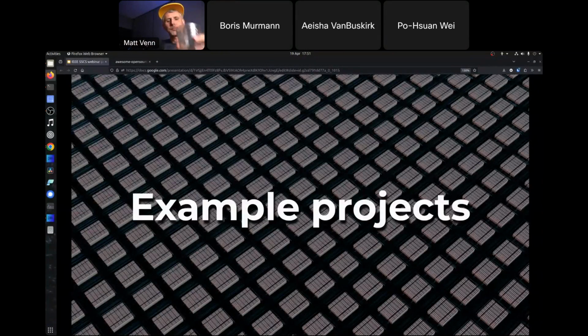What are the limitations of open source tools you shared in terms of process nodes or number of transistors, etc.? I would say probably 10 million transistors, order of magnitude. There's a lot of development. One of the big bottlenecks is that there's maybe 10 or 12 tools in the whole ASIC flow. One of the bottlenecks is Yosys, maintained by YosysHQ, but we are doing a lot of development work on that at the moment. And we've got a fair amount of investment coming in to improve the ASIC performance on there.